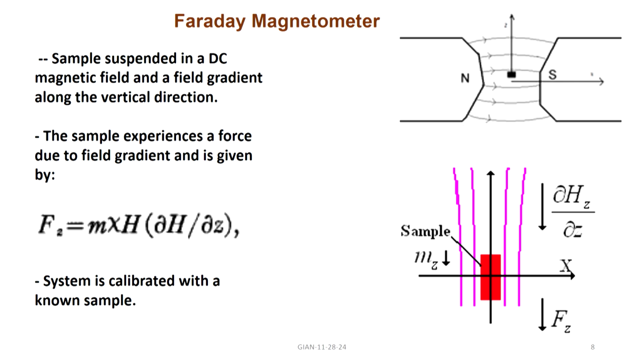So, this force will pull the sample down, and there is a control electronics with a photo detector. So, when the sample moves down because of this magnetic force, it allows more light to go into the system. There is a photosensitive detection that will sense the deflection of the sample, then it will send a signal to correct for that. So, ultimately what you get is the unit produces an output which is proportional to this force, and the expression for the force is given here.